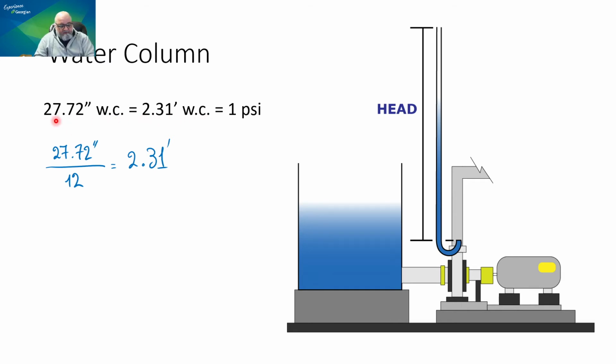This number is important for gas technicians because we do measure the gas pressure and air pressure in inches of water column. But once you start talking HVAC and hydronic heating, which is coming up in the summer, you have a hydronic heating course in the summer, you are also going to talk about feet of water column. As long as you remember this formula, you are good to go. And again, you don't need to memorize both sides. You can just memorize one of them, whichever works for you.